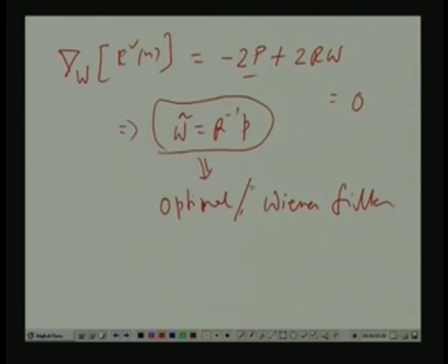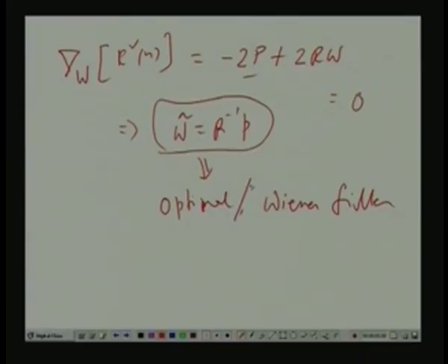In practice, if you know R and P, fine, you can calculate this R inverse P, but the problem is R and P are not always known. In that case, you have to supply this information externally. This actually gives rise to the interesting case of the adaptive filter. When R and P are not known, or when the input statistics or the joint statistics between Dn and Xn change from time to time, you cannot have one filter designed once for all. So, what should you have?